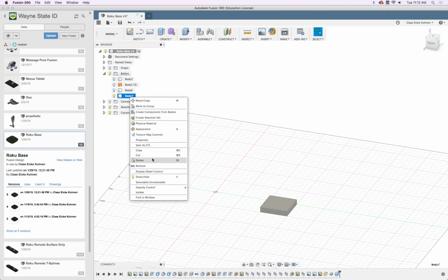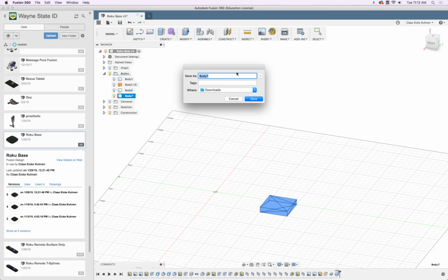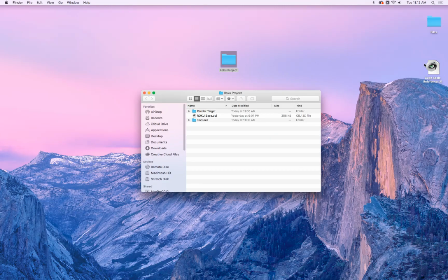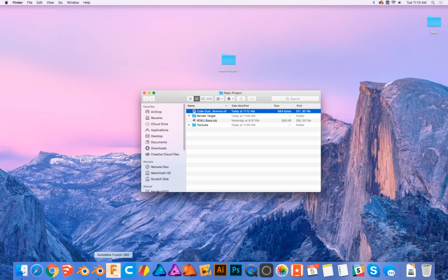So this cube I could click Save as STL and go OK. Let's say cube scale reference. And this trick I'm showing you right now is literally a trick that works not only from Fusion to Blender, it works among all programs. Because sometimes when you export mesh objects, scale is always an issue to establish accurately. So I copied that STL object into that folder.